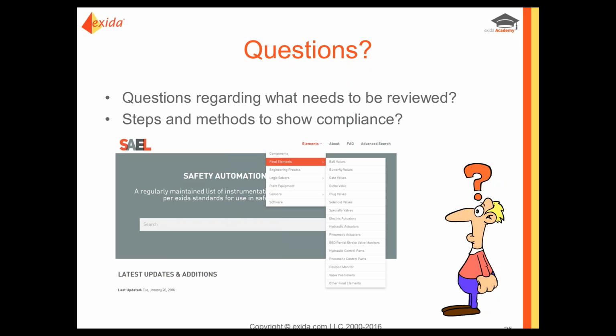Should we specify a certified integration process in the specification for on-off valves used for safety applications? I would probably recommend either that or listing the minimum evidence documents you'd want to see. So, say, must provide calculations, must provide test plans, must provide ISO cert. If you ask for it up front, you've got a much better chance of getting it, and it helps the integrator or whoever is supplying it think about those steps before they're done.